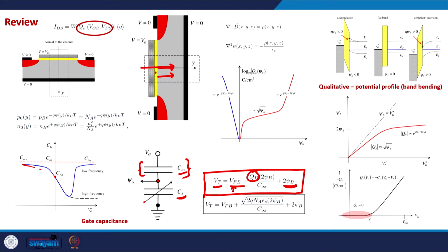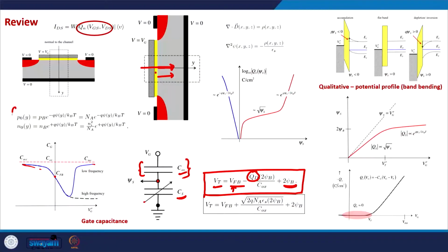However, if we talk about the capacitance of a MOSFET, in that case the capacitance will look like the low frequency plot, because in a MOSFET the inversion layer, the minority carriers, can come from the contacts, and the mobile charge carrier density inside the semiconductor is given by these relationships, which come from the carrier statistics in semiconductors. So, this is all what we have seen so far in the discussion of the conventional electrostatics of MOSFETs.